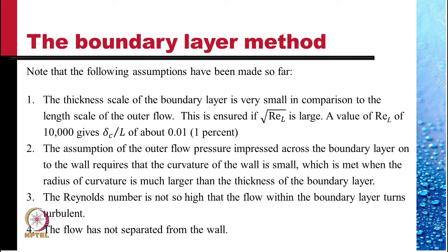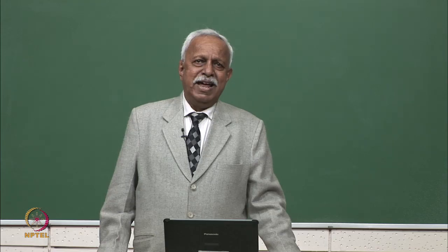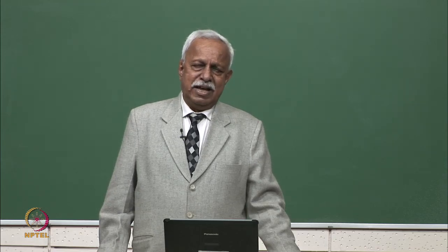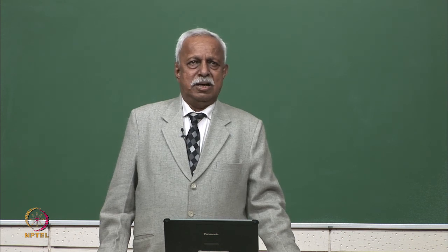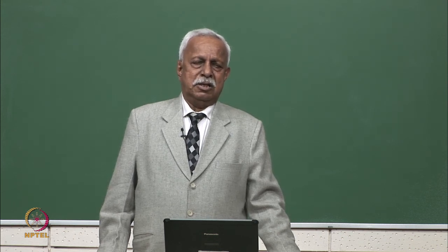We have also assumed that the flow has not separated from the wall. It is an important condition because once the flow separates from the wall, the boundary layer is no longer thin, and the boundary layer assumptions break down.